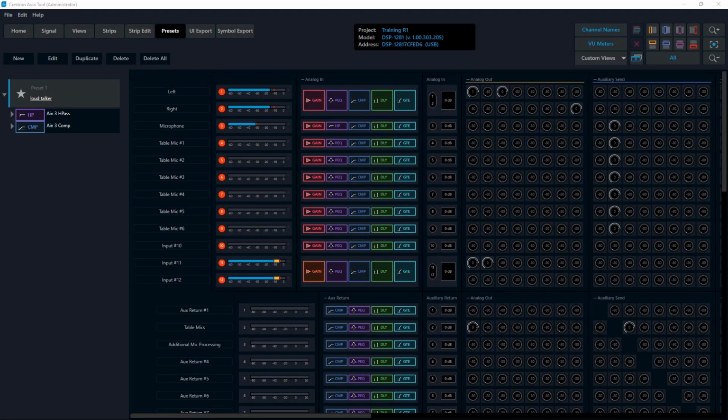Nearly any of the DSP controls can be part of a preset. Presets are also a great tool for switching signals through the matrix. Offline, I reconfigured the two stereo inputs on the DSP. One analog, the other is Dante. I can set up a pair of presets that will toggle mute back and forth, feeding an aux bus.